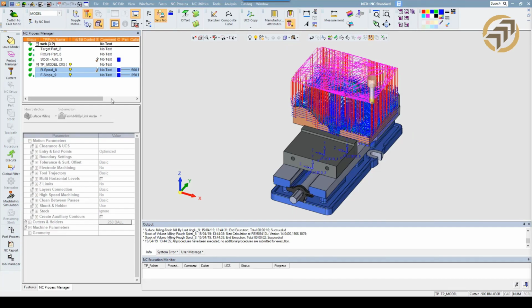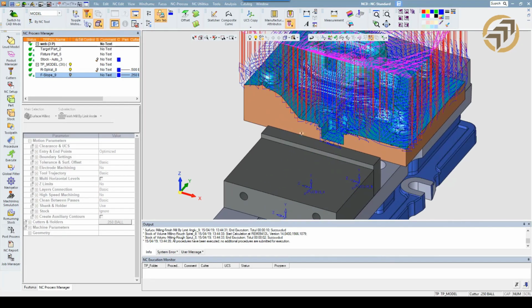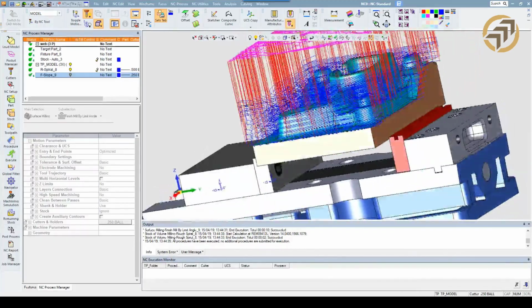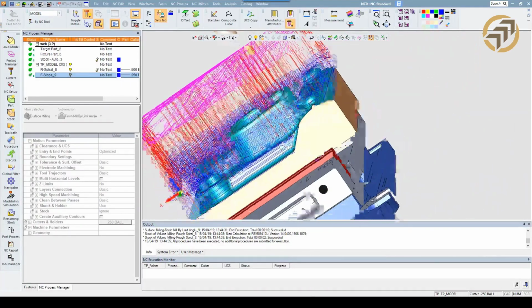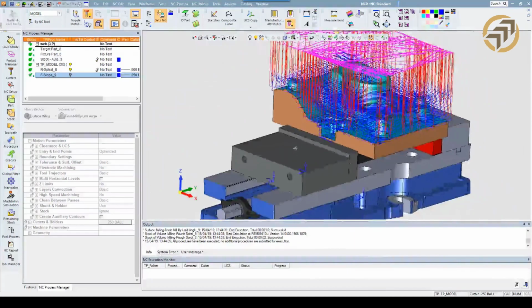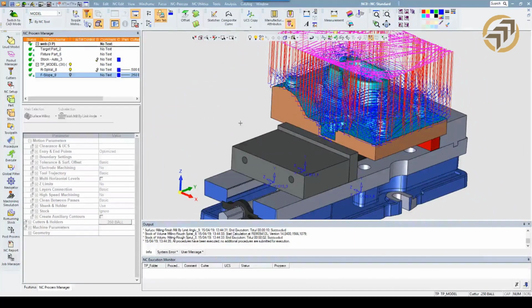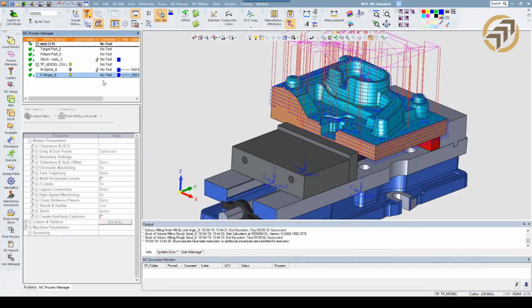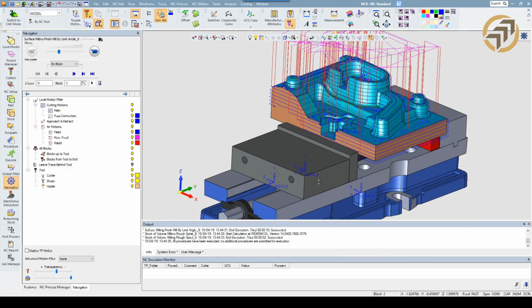And that's finished crunching, so let's take a look at this. I'm going to take a look at the roughing procedure first. You can see it roughed it down, no part surfaces picked, using safe mill. Avoided the fixture and roughed to within +10. Now on the finish mill path, I did not pick any contours purposely because I just wanted to show again what safe mill does.